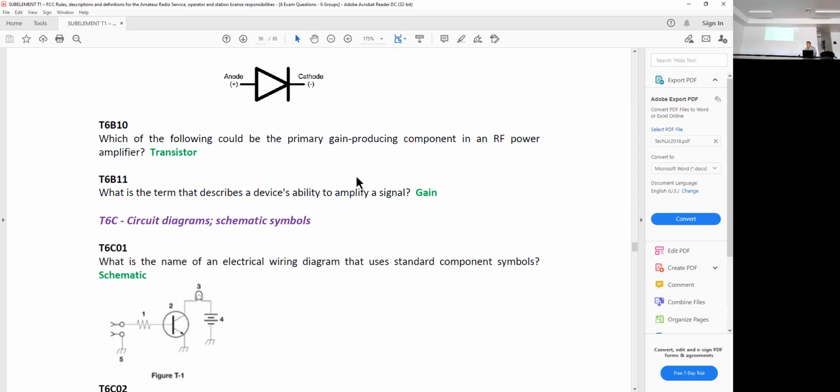Build your antenna. Yeah, well, an antenna is always better for a couple of reasons. It gives you more signal with no increased noise. Anytime you amplify a signal with a transistor, yes, you get more signal, but the noise that was in there with that signal also gets amplified.